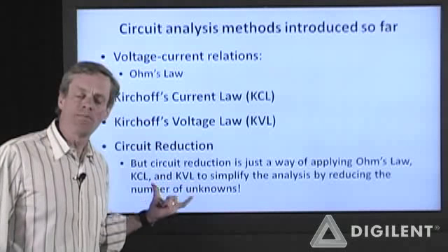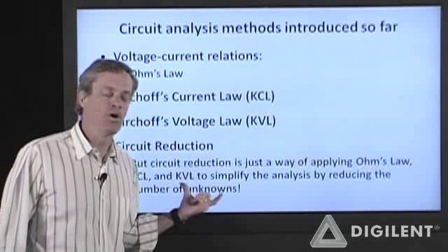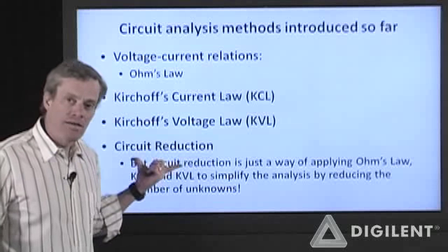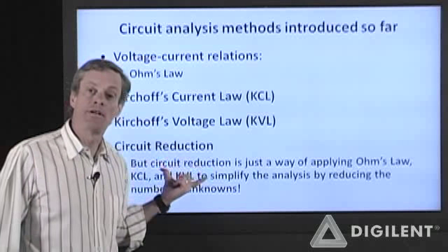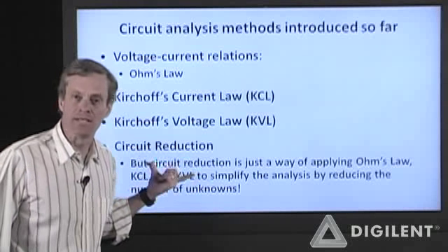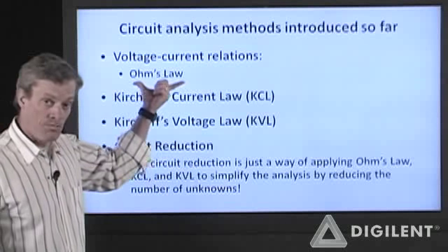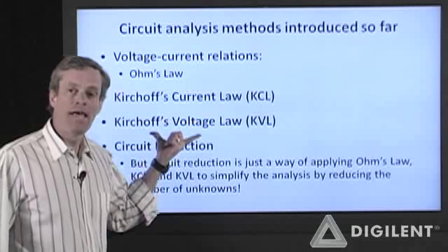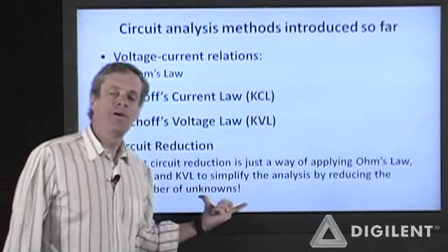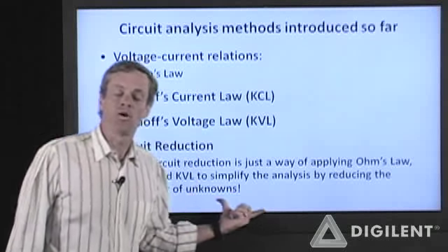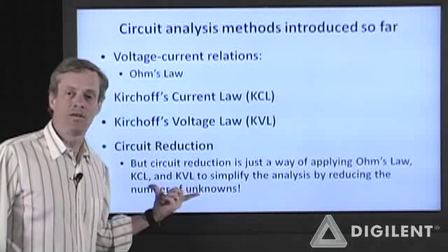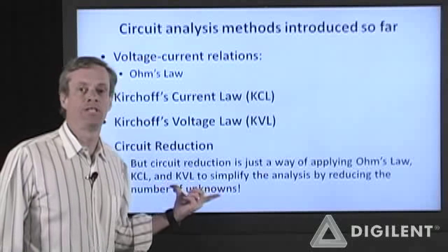Now, there's something very important I have to note here. I claimed that circuit reduction was another analysis technique. It isn't. It's a special way of applying Ohm's law, KVL, and KCL in order to make your life a little bit easier. We didn't do anything new when we were doing circuit reduction.